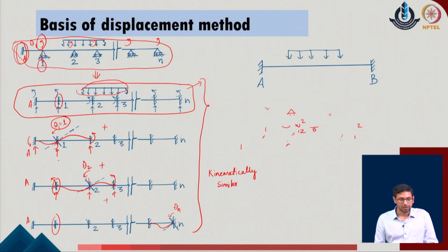With all these systems, the condition of restraint is followed except for one system where theta 1 is provided to the given system. And if instead of a unit theta 1 it is the value of theta 1 only, the original rotation of the given system, this system becomes the same as the original system considered in the given problem. In a similar manner, I can take the summation of all these systems together and calculate that while all the systems have restrained degrees of freedom, only one system, with respect to theta 2, is released, and that is the same as the original condition of the rotation in the original problem.